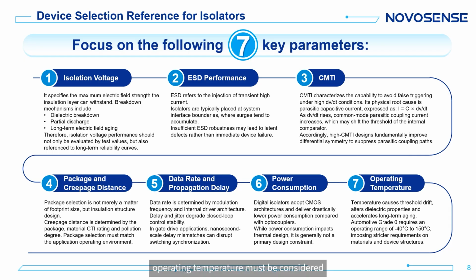Finally, operating temperature must be considered. Temperature affects threshold drift, dielectric characteristics, and long-term aging. For automotive grade 0 applications, devices must support operation from minus 40 degrees Celsius to plus 150 degrees Celsius, placing stringent requirements on materials and process technologies.